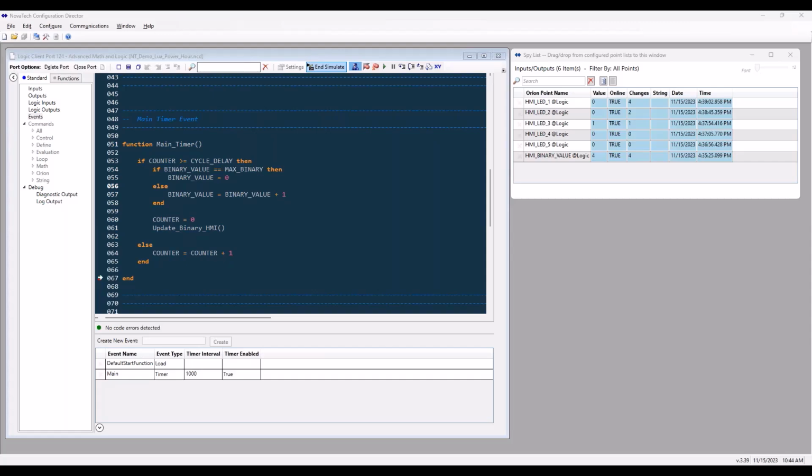So there is the option to set breakpoints. As you see, I've set a breakpoint here. It's kind of difficult to see, but it's this red circle. So that'll be an additional ending point when you're stepping through the logic. If that makes sense, you should be able to click on that breakpoint, and you have the option to clear all your breakpoints. So if I click on that button, it goes away.